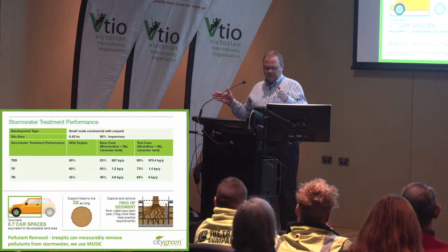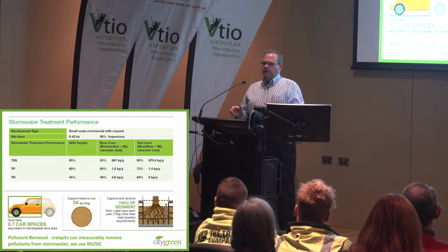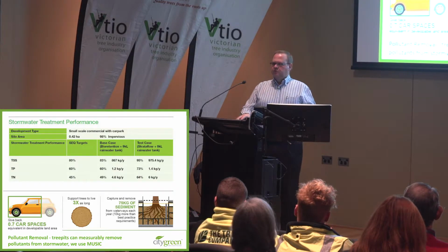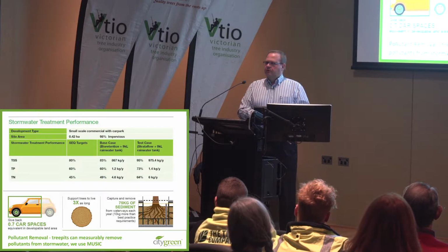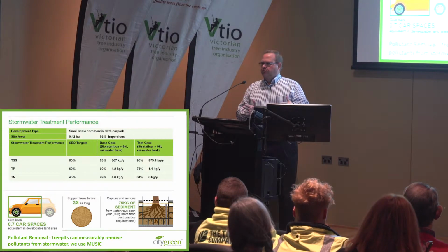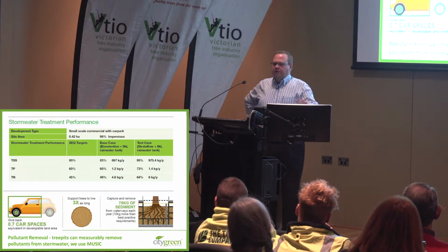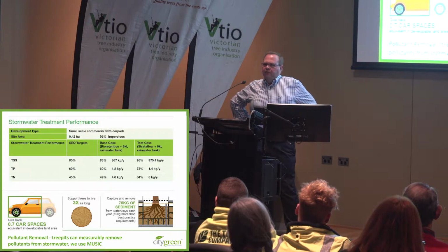i.e. there's a band, an optimal band between catchment area and surface area of the pit. If it's too little, if the catchment area is too small for the tree, well, the tree won't be getting the benefit of the water that it could be. If there's too big a catchment area per tree pit, the tree could be getting too much water, if that makes sense.